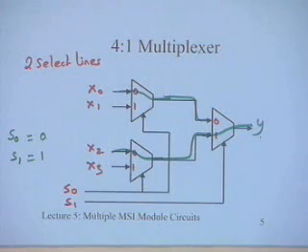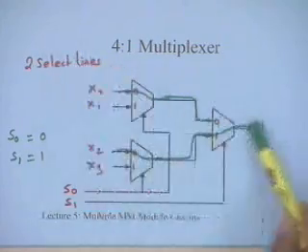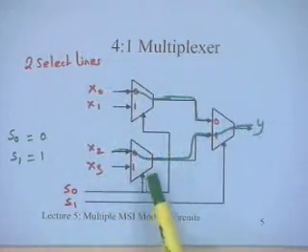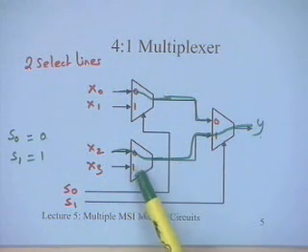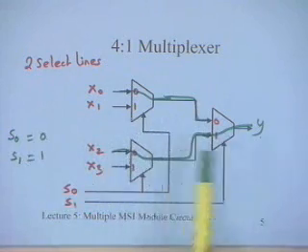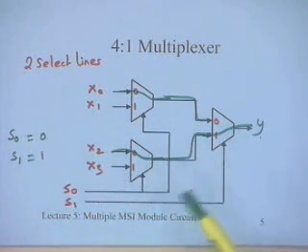So it's very clear that the way you can implement a larger multiplexer is by having a number of levels. Again it's like a tree, of course it's an inverted tree, you're converging. There it was diverging, and here it's converging. So if I'm using a 2:1 multiplexer and I have 3 select lines, I will have 3 levels. If I have 4 select lines, I will have 4 levels. And simply I can implement this.